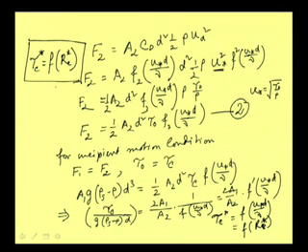Well, up to this much the analysis that has been carried out, of course, we can also do by dimensional analysis, considering what are the factors influencing. I can give a brief view of that, but right at this moment we can consider that tau c star is equal to a function of the Shear Reynolds number. Then Shields did a lot of experiments, and a lot of data were collected by his followers also, and then a graph was drawn.